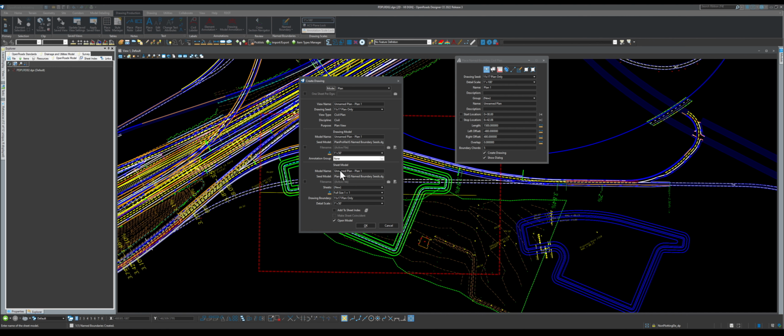And then the detail scale also I want it to be 100. And the sheet I want it to be new, and the sheet scale is always 1:1. So just remember this: this scale matches this scale. If it's 100 in a drawing model, it's 100 for the detail. And then for the annotation, you can select whatever your workspace has.